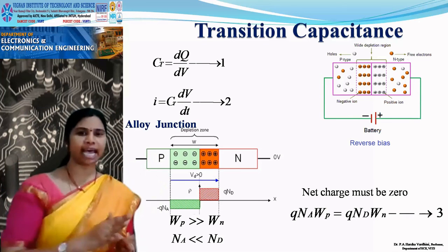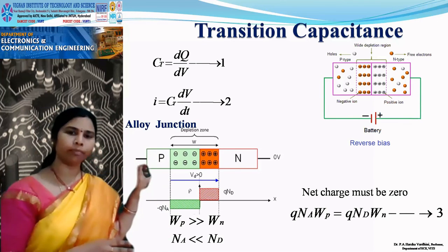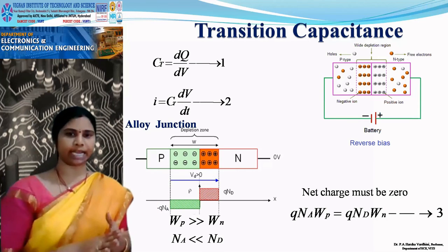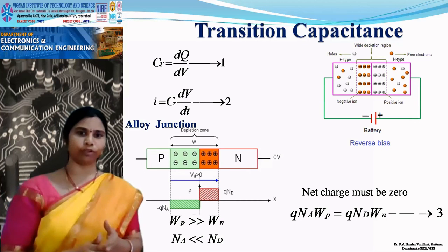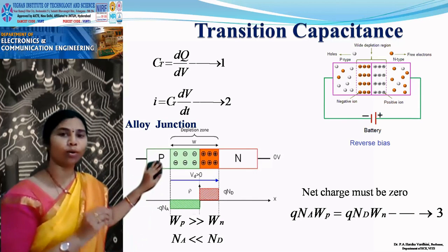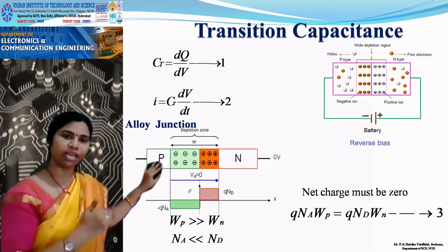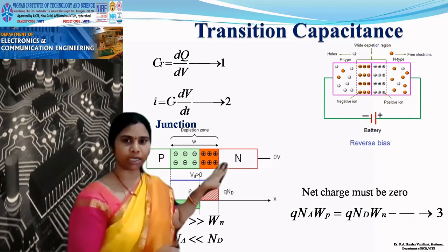The electrons have disappeared because of recombination with the indium holes you have added to this n-type germanium bar. So whatever holes are left over in the indium material are there in this p-type material. So you can say the hole concentration is very, very much lesser than the electron concentration in the n-type semiconductor.